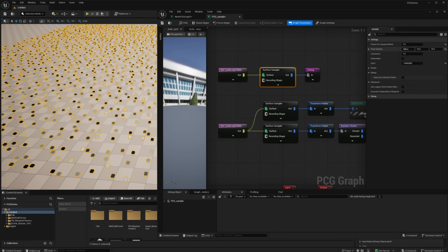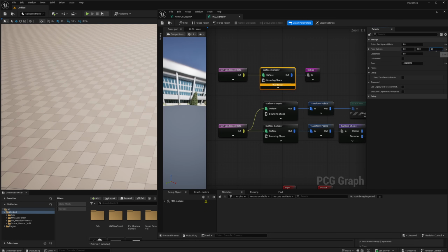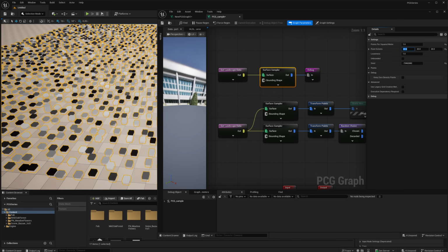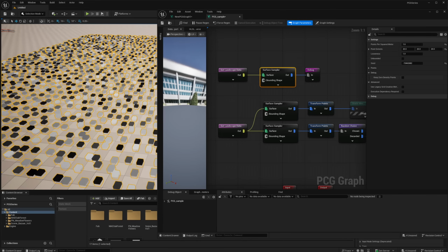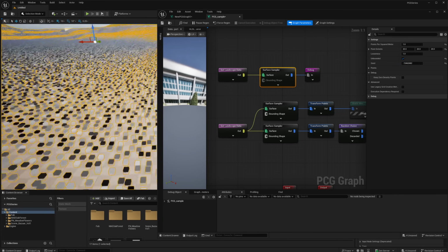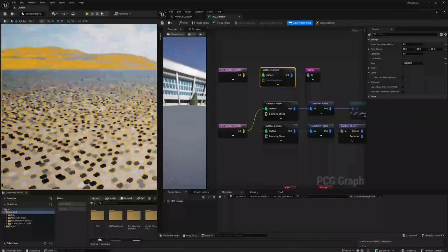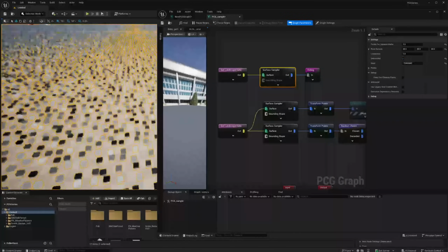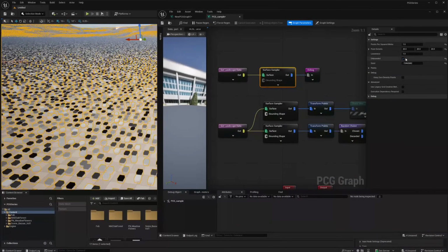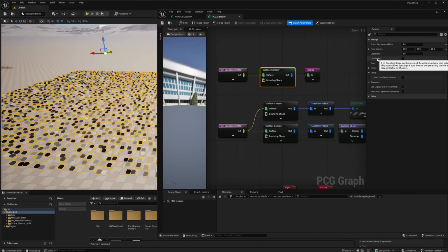The extents, as you remember from the last tutorials, is the extents of each point. And this unbounded checkbox will apply these settings to the full landscape, not just the area in your bounding box. But always when you use unbounded samplers, you need to be careful because there are some limitations to this.